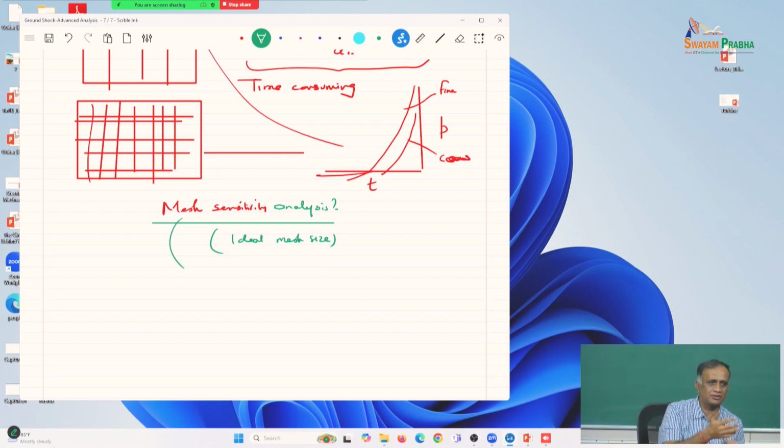The mesh size also depends on the type of material for that particular simulation. You take some other experiments, maybe the mesh size is a little different. So we've gone with recommendations of mesh sizes for this type of, it depends on the material behavior as well.